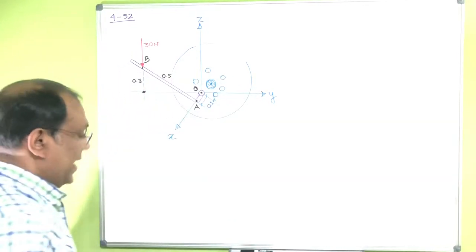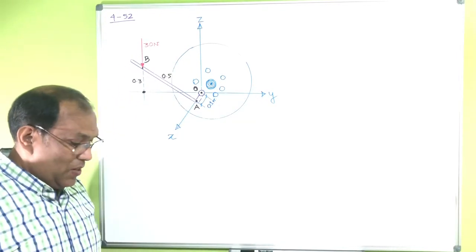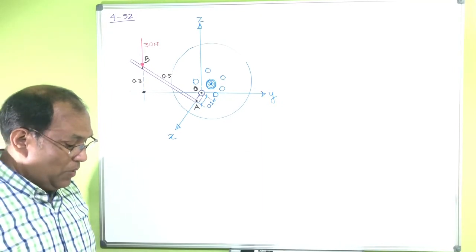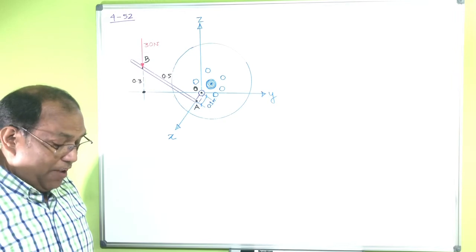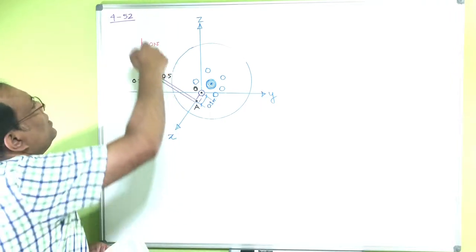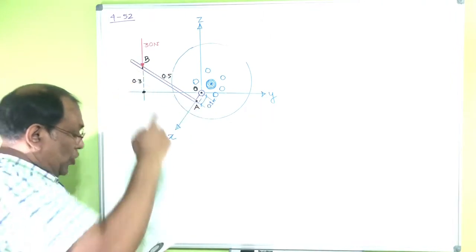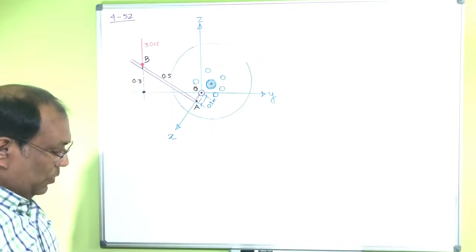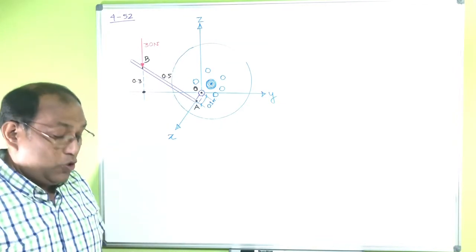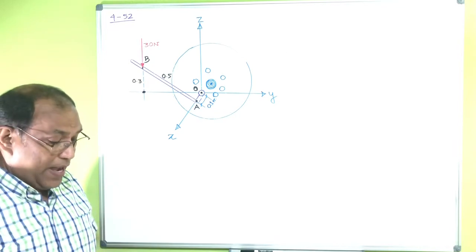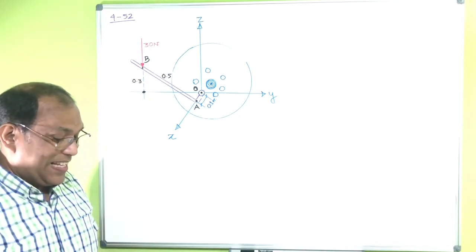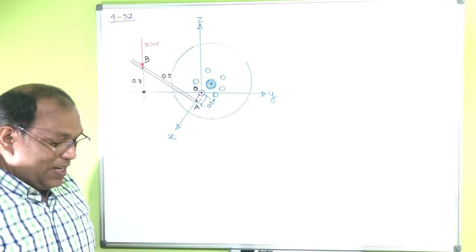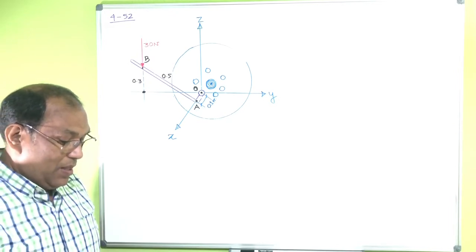It says that the lug nut on the wheel of the automobile is to be removed using a wrench and applying the vertical force F, which is 30 Newton, and that's your wrench here. Now it says determine if the force is adequate to provide 14 Newton meter of torque about the x-axis, which is initially required to turn the nut.